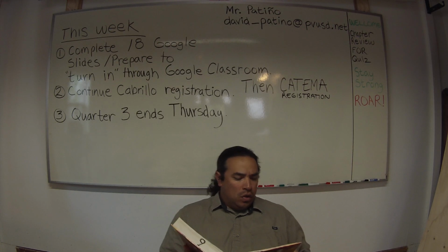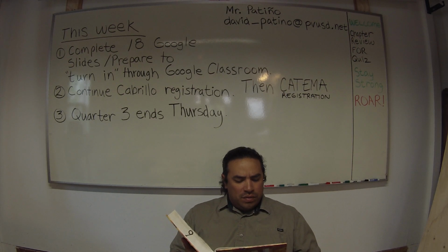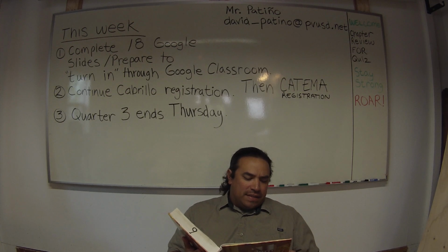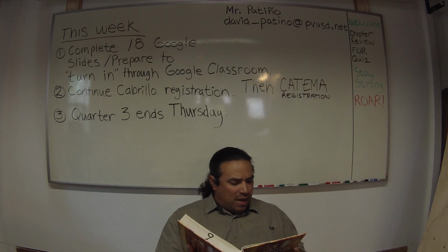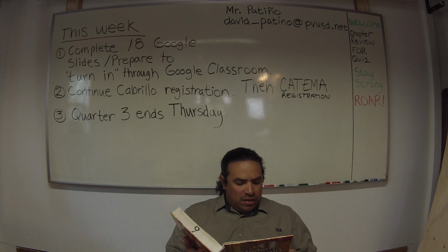Next section, wood structure and growth. Wood is made up of long, narrow tubes called fibers or tracheids. The cells are no larger around than a human hair. Their length varies from about 1/25 of an inch for hardwoods to approximately 1/8 of an inch for softwoods.